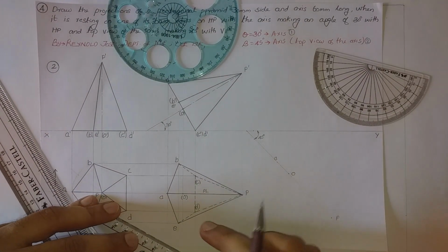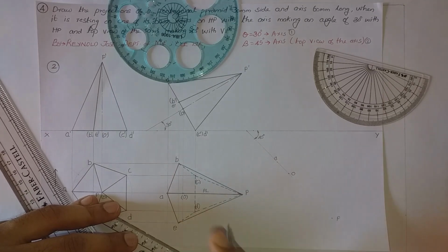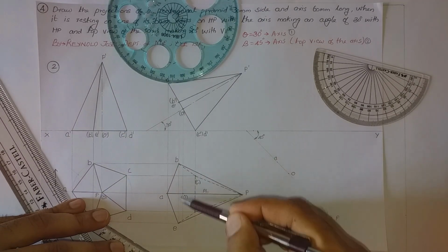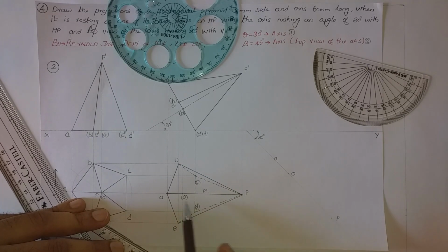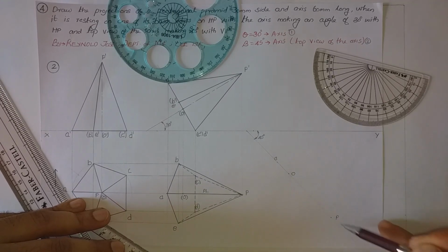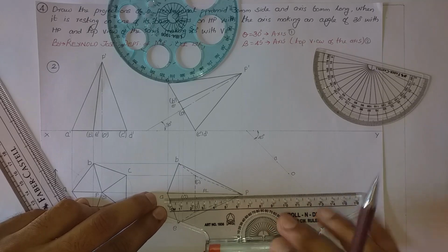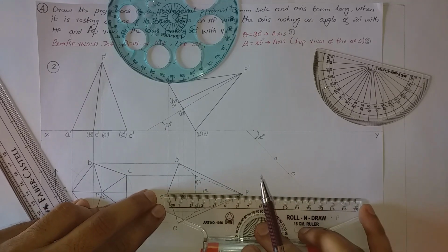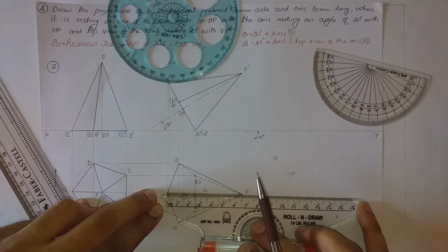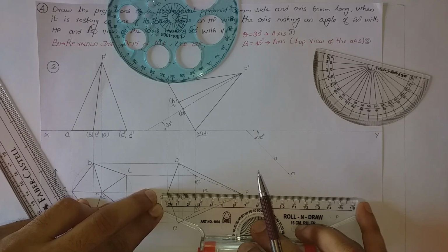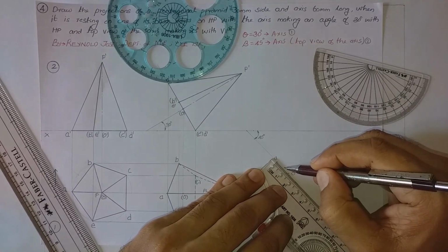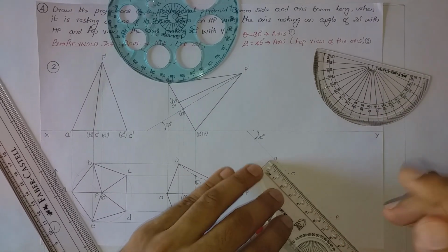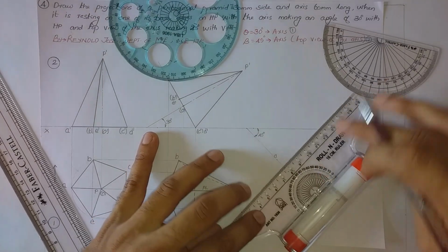Now we have to mark D, C and BE. BE is perpendicular to PA. So we shall mark this perpendicular line onto this particular line. From A to this perpendicular line, the distance is approximately 10 mm. So from point A, I am taking 10 mm, I am putting a dot here, and through this dot I am drawing a perpendicular line.